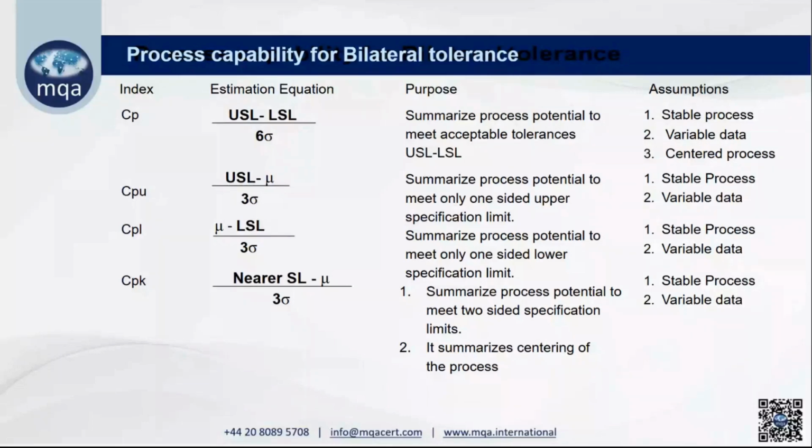See, I can give the example of a bearing and shaft. When there is a bearing, the bearing ID has to be on the lower side. So it will be 50 mm minus 25 microns, 0.025, right? Because the bearing has to be smaller as it is a press fit.